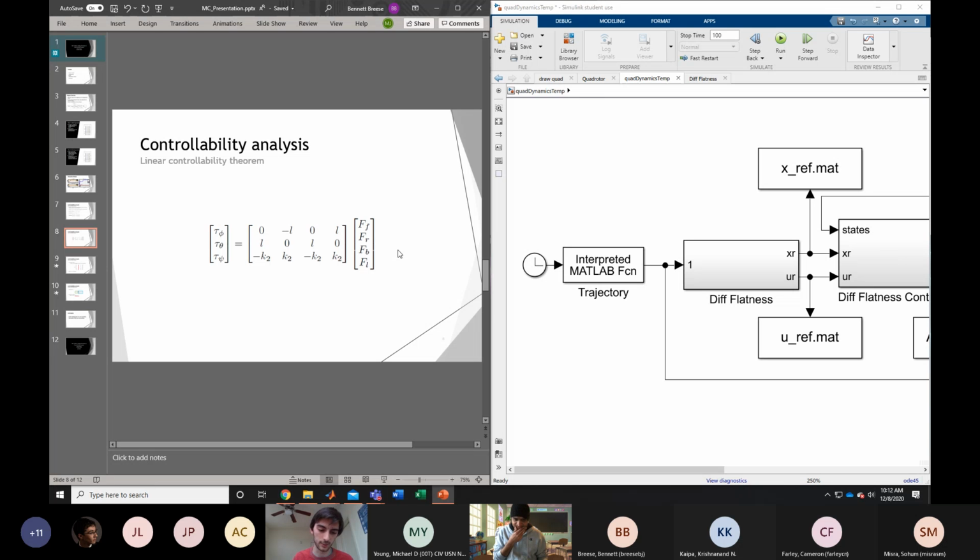That's why we can assume that phi dot, theta dot, and psi dot are almost equal to p, q, and r. For the overall operation, there's a PD controller that controls attitude, and the LQR is in charge of controlling the position of the quadcopter. Okay. Thank you.